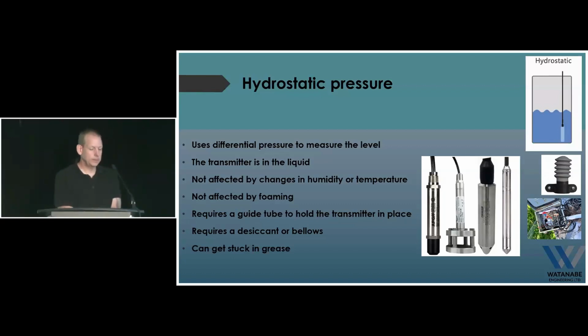And the bellows system, I have more success with. They tend to last longer. I've seen many, many stations where there's desiccant used, and desiccant starts to go pink when it's wet, and I've seen some of them that are almost bright red, so they're not doing their job at that point. So if you are using these systems, please change the desiccant regularly, keep an eye on them, or make sure you've got a good bellows on there.